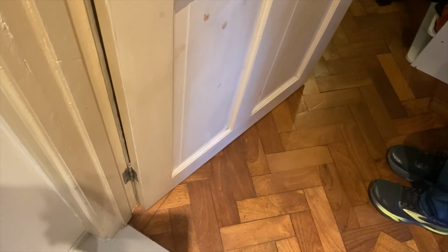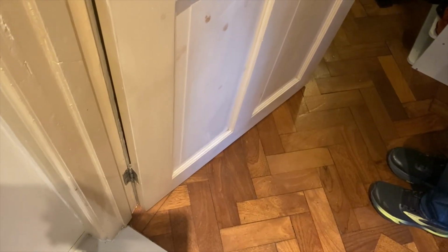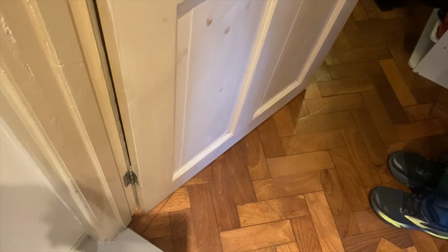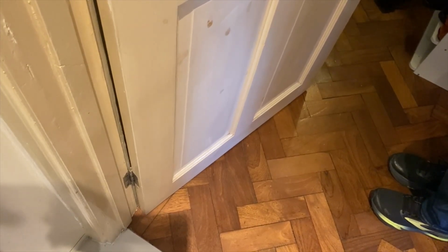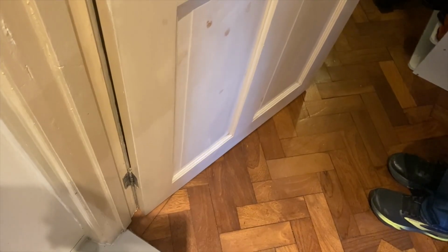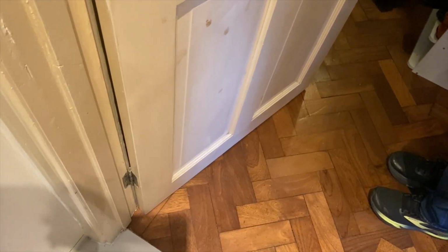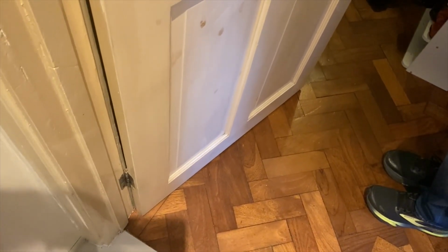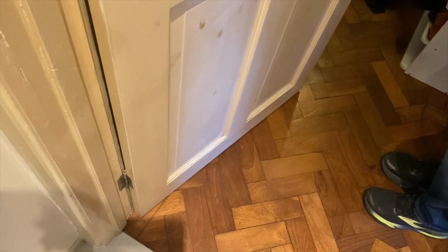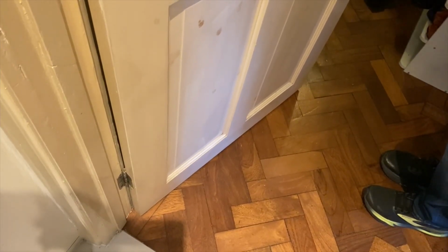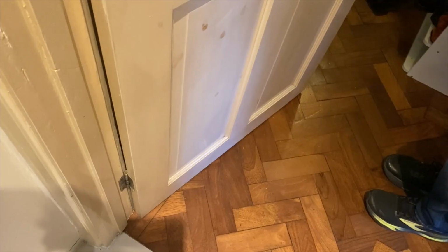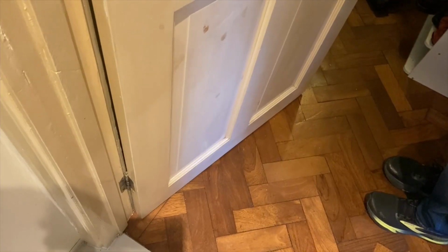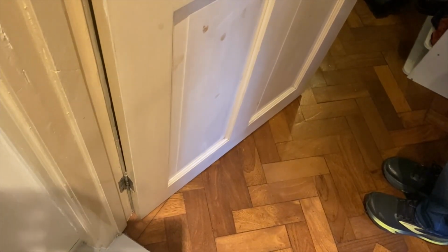Number 2 is, as part of the building's design, you've got large lintels which will almost certainly have metal in them, and the metal gets cold rapidly. Irrespective of any insulation in the cavity, it will get cold, and so you're getting mold around the top of the lintels. But you're also getting mold in the zones where you can't get the easy transfer of heat from the radiator. So a cupboard, as an example, or behind the curtains, or the window reveals. All of those.